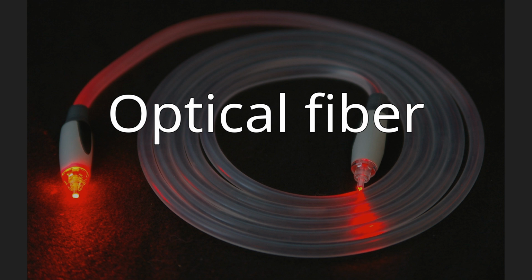Multi-mode fibers generally have a wider core diameter and are used for short-distance communication links and for applications where high power must be transmitted. Single-mode fibers are used for most communication links longer than 1,000 meters (3,300 ft). Being able to join optical fibers with low loss is important in fiber optic communication. This is more complex than joining electrical wire or cable and involves careful cleaving of the fibers, precise alignment of the fiber cores, and the coupling of these aligned cores.